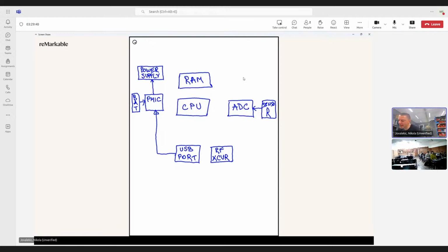Simple UART is actually connected to this component, which we named here CPU. Why UART? UART is used because we have low speeds here. We have a part here which is purely digital, and it just provides digital information. So we don't need to worry too much about this.